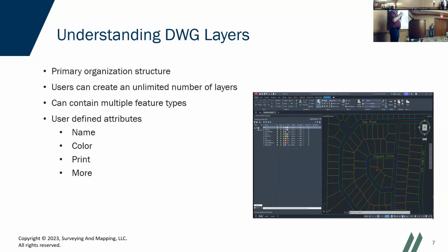So this becomes problematic because in GIS, if you've never done CAD, you'll never understand this. Why am I getting these weird things on this layer? It says it's sewer line. Why am I getting water lines on here? Right? So, because there's no enforcement of just because you name it, it's supposed to store this, that it has to store that. And that's just so alien to us because we're very, if it says sewer line, we only put lines in it, we're only going to do that. That's not in CAD. Matter of fact, in CAD, and I've seen this done, I can do everything in one layer. So when you create a new CAD file, it starts with layer 0. You can draw everything in layer 0 and individually as I draw a line. Okay, I want this line to be red and dashed.